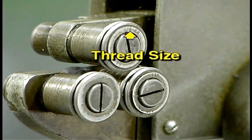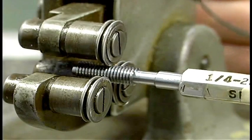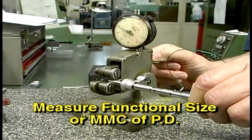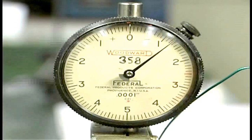The rolls mounted in the gauge are selected based on the thread pitch and diameter being measured. Multi-threaded rolls measure the cumulative effect of thread variations across a number of threads they engage. In effect, they measure the functional size or maximum material condition of the pitch diameter. A dial indicator gives a reading of the measurement.